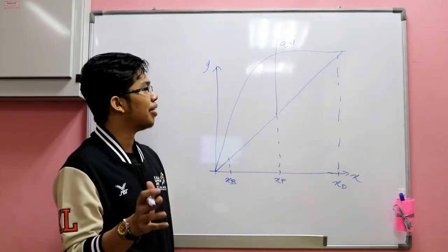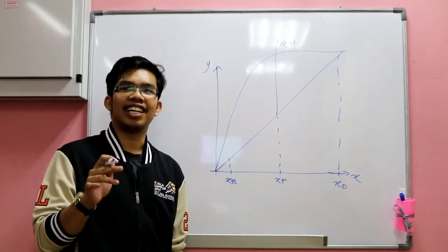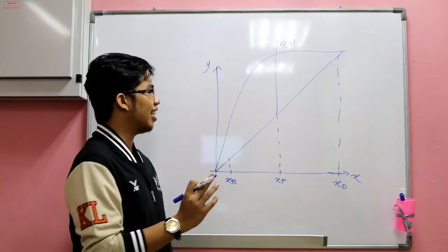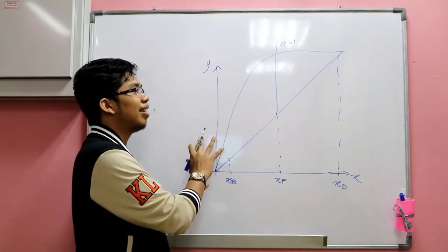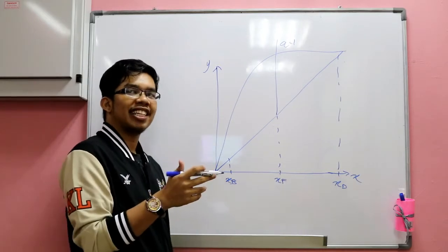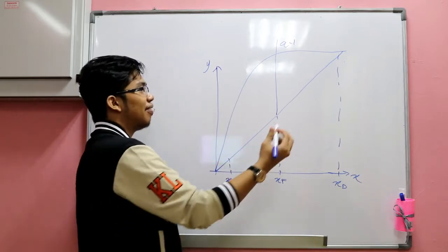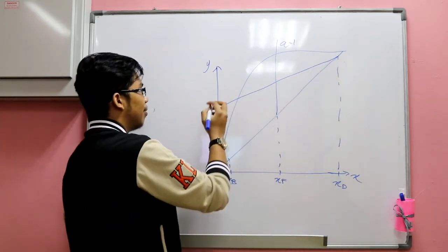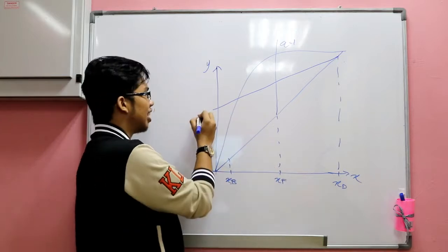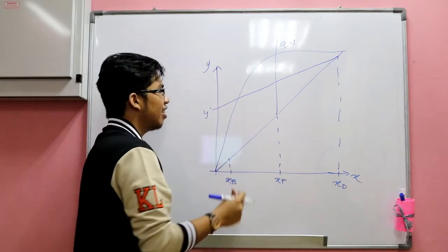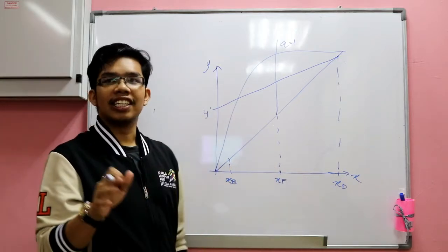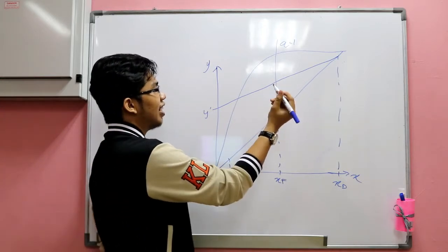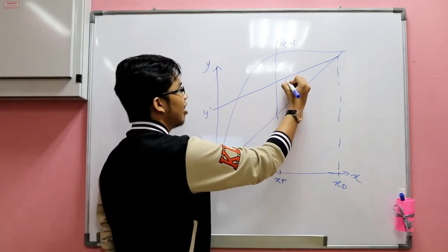Okay, and then we will draw the rectifying operating line. For the rectifying operating line, we will first calculate the y-intercept based on the formula given, and then we will draw it from the x distillate until the value of the y-intercept that we get from the question. And then for the stripping operating line, we will draw it from the intersection of the q line and the rectifying line